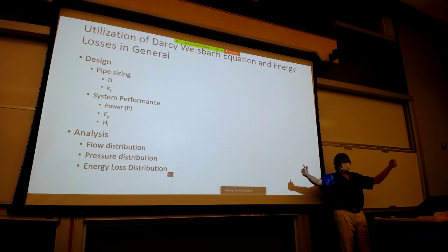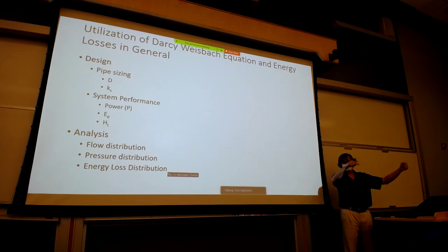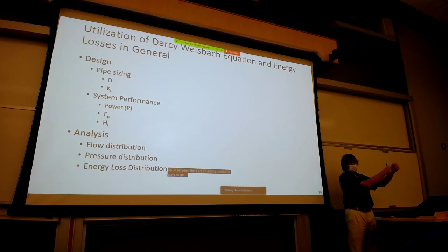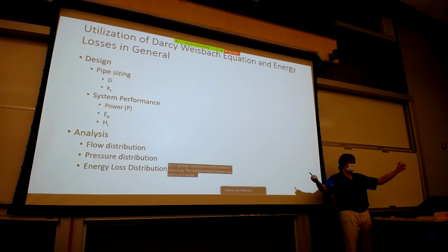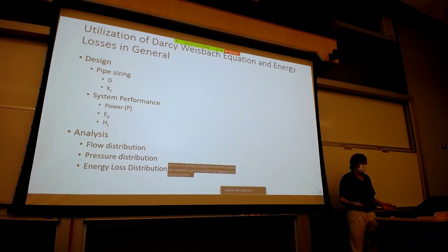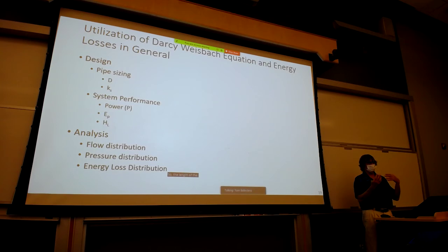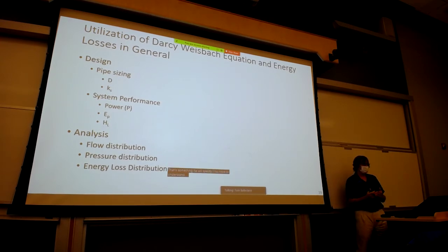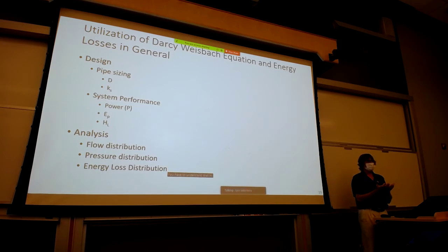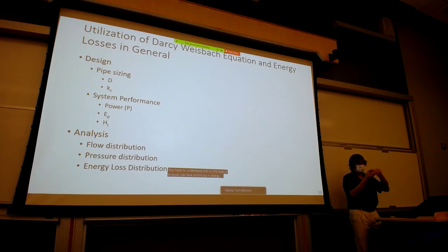So in between, there are an infinite number of ways to go. The shortest distance between two points is, of course, a straight line, but not all pipes can necessarily go in a straight line, especially in a big distribution system. So the length of the pipe, of course, is certainly in your purview, but very often we're looking at the diameter and then the material, k sub s. That's something you will specify. You have to understand that in this type of analysis, we have continuity and energy. Those by and of themselves will not be able to solve all of our problems.